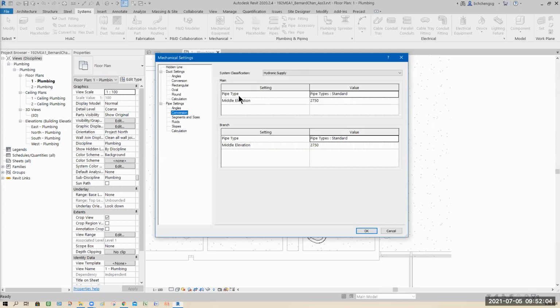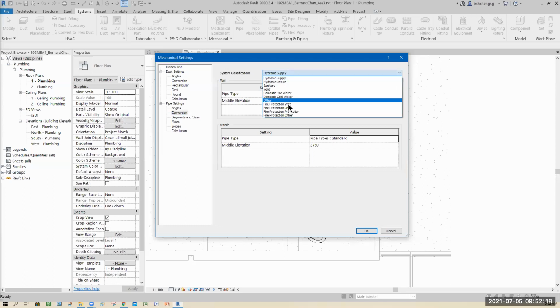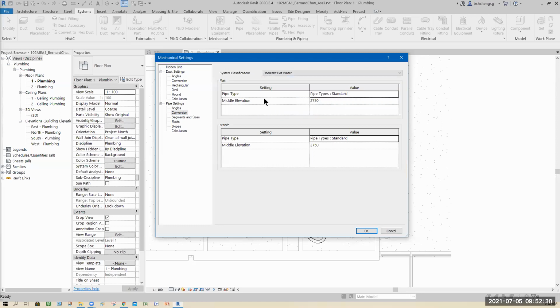Conversion, for instance, this is important. Plumbing, we have 2 different pipe or even 3, like copper, stainless steel, and PVC. And it depends on what type of system you are using. For instance, our hot and cold water. Hot and cold water normally will be stainless steel or copper. So you need to configure. Then how they do the measurement, measure from where. So all this can be preset.